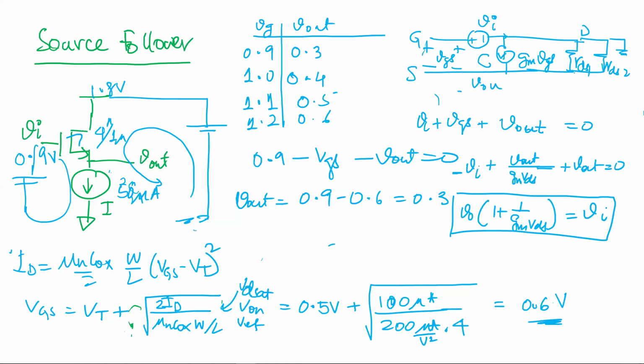And in small signal, if you do it, like I said, it should come out pretty close to that, because you have a finite output impedance, so it won't exactly follow, because this one will go up to the point where it is following that curve, right? If RDS was infinite, then this term will become 0. Ideal RDS is infinite; if it is not infinite, then it will change by some amount. You got it? Okay, so at least intuitively you follow that, right?